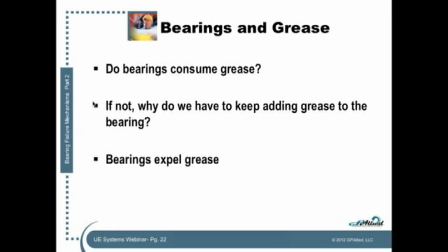And while it's in there, there's going to be some heat in there. The heat gets transferred from the bearing, specifically in the load zone, to the grease, and then when that grease moves out of the load zone, the grease can dissipate the heat to the air that's in the bearing. Now, at the same time, that grease is also catching, if you will, contaminants that may have gotten into the bearing because of seal damage or because of poor lubrication practices, and we actually pumped contaminants in when we pumped in the new grease. So the grease's job is to remove the heat and the contaminants from the load zone, from the interfacing spot between the balls and the race.